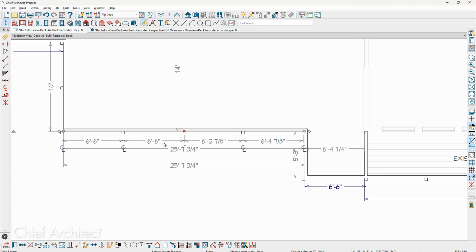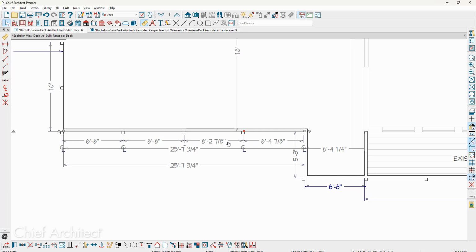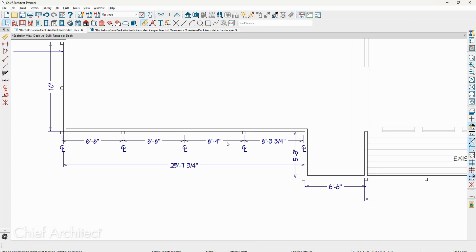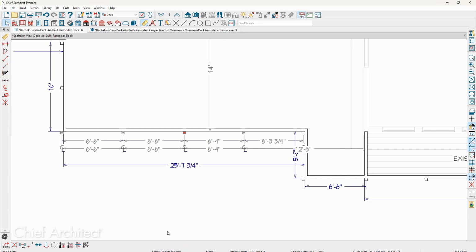We'll go ahead and click on the next one, position that one 6'6". So it's easy to move the newels. I just click approximately where this is. We'll set this one to be 6'4". To use that tool to exactly position your newels, you can also click on the wall itself. There is a tool down here called Move Newels. This gives you access to the newel movement, so you can click on there and move it.